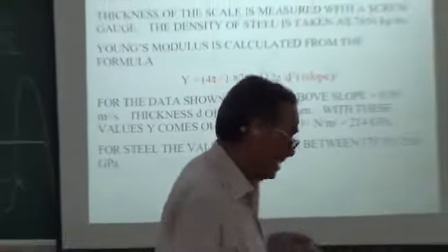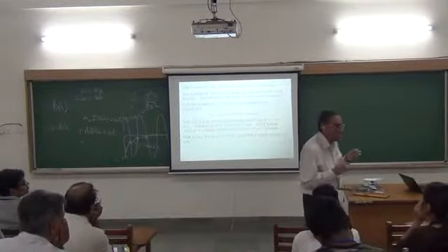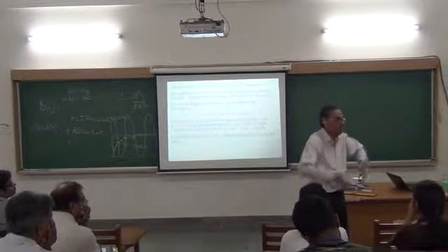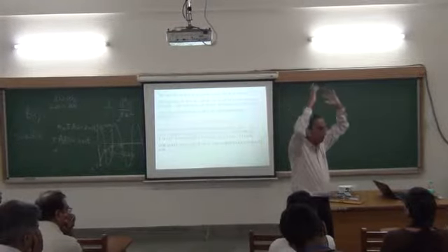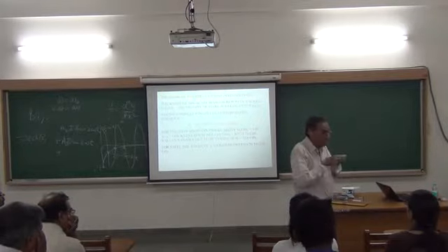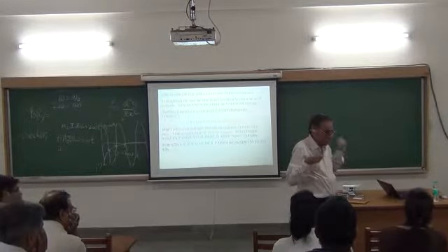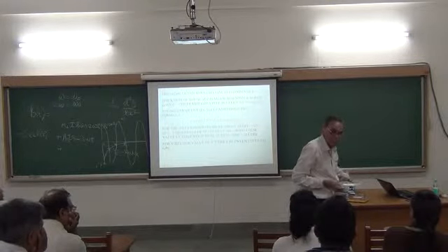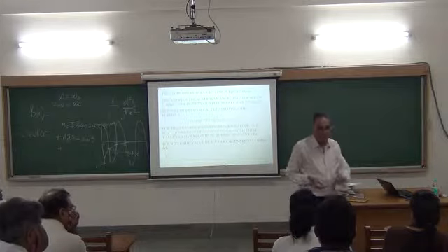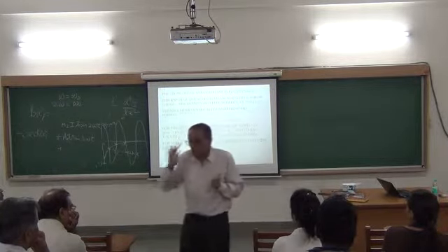You can prepare materials called metallic glasses in the form of thin film. You heat the metal to a very high temperature, cool it very rapidly. It forms a metallic glass. You can make thin ribbons of the metallic glass. You want to study the elastic property, then you use this technique. You put the strip. The experiment is more complicated.